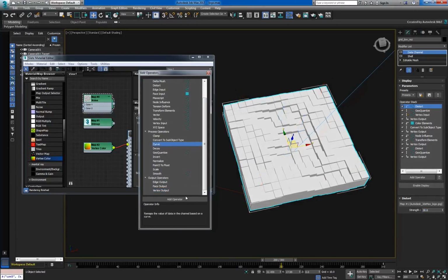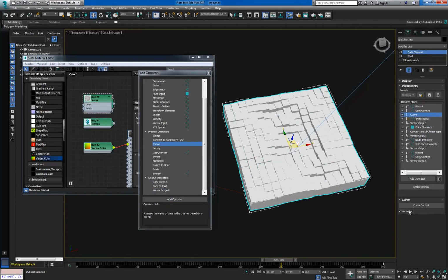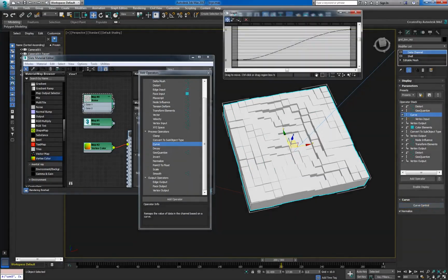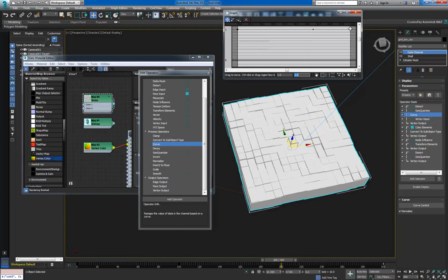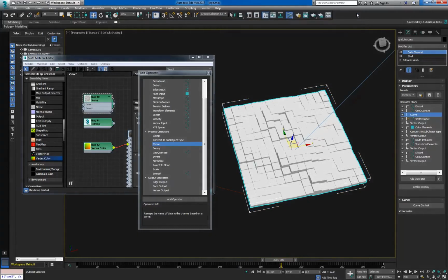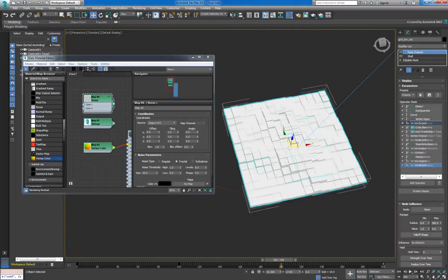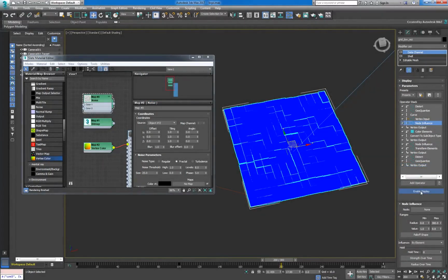To change this, we'll need a curve to remap the data. Enable the Normalize checkbox to make sure the curve operates on the whole range of data. We'll remap lower values to higher ones and higher values to lower ones by reversing the curve's endpoints. We can now add one last node influence to focus the bulge closer to the 3 and to reduce the text extension in the lower right corner.